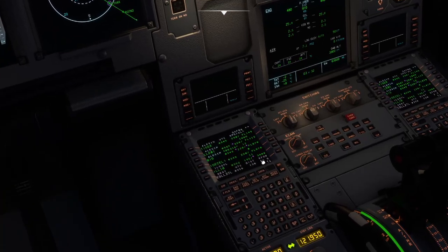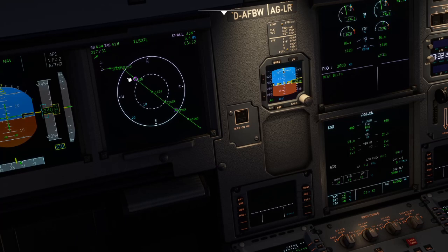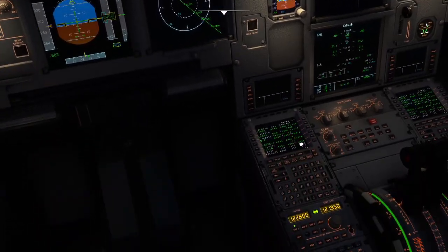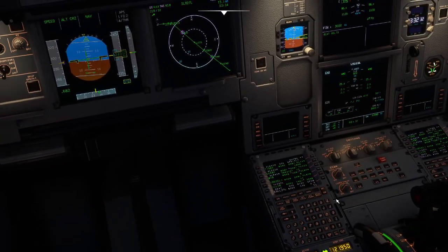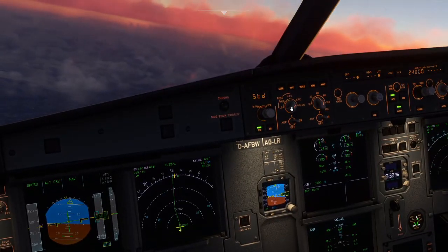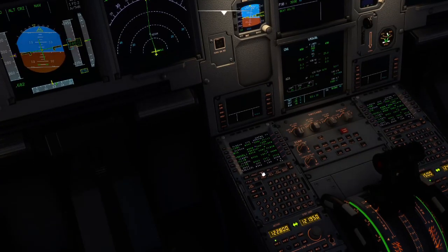You can see if I zoom in, the jet has set a transition of 3,000 feet at the top of that approach, which is pretty standard for most ILS approaches. You'd expect most ILSs to kick off from around 2,500 to 3,000 feet above ground level. We know Heathrow is going to be almost sea level, so around that 3,000 feet is what we're targeting. That is what we've got. Happy days. Back in arc mode, I've got a little bit of time to top of descent. Yep, we've got time here in the cruise. So we can look at our next little problem.